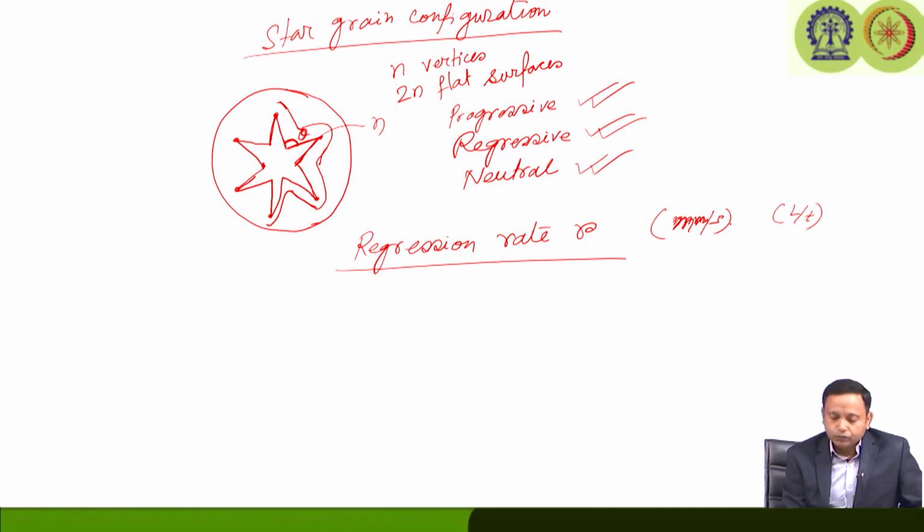Okay. So, now the question is how it is defined, how it is determined how many millimeters per second has regressed for a particular propellant. So, there are different testing methods. Choosing a certain propellant, of course, is very tricky. In order to choose a certain propellant, we need to understand the burning rate, how the propellant is burning.